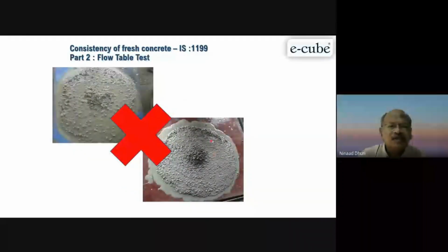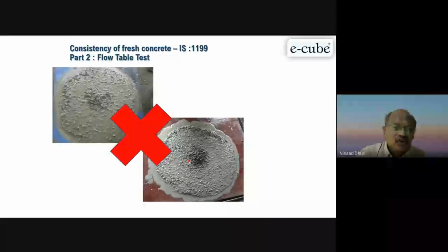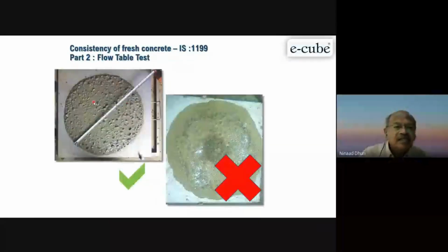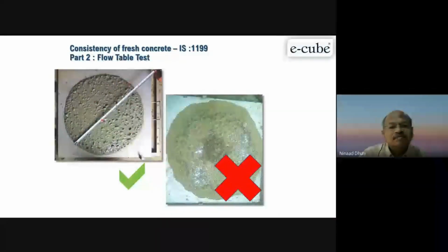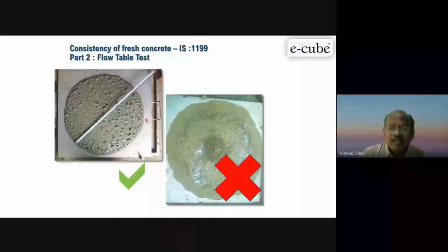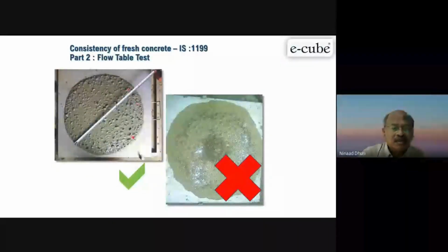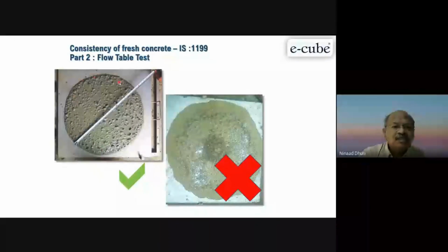See, this is also what we have taken as an actual photograph at the site, how the concrete is behaving with the vibrations. So what we are looking at is this type of concrete always. It is also flowable, about 600 mm flow is there. But still, you can see the aggregate has all come to the circumference here. All the face, there is no segregation.